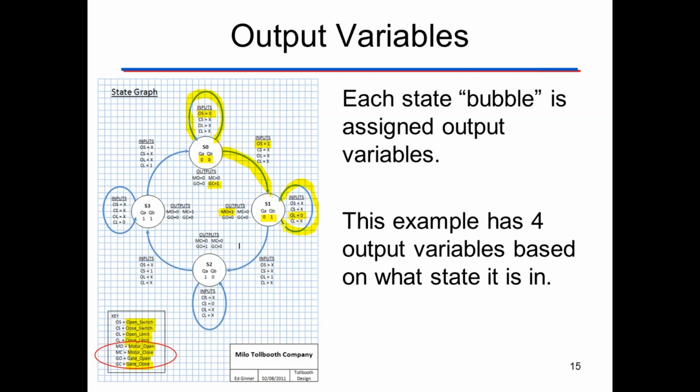When the open limit switch occurs, when we get this open limit switch equal to 1, all of a sudden we're going to make a transition. We're still in state 1. This is the second part of state 1. Remember, the first part of state 1 is this, while we're waiting, the motor's running. The open limit switch is up, so the open limit switch is equal to 1. That gives us this transition down here to state number 2.